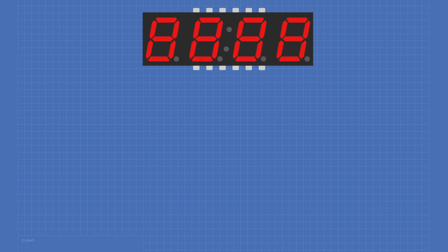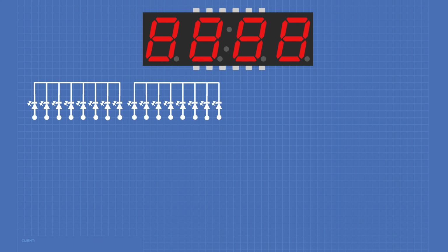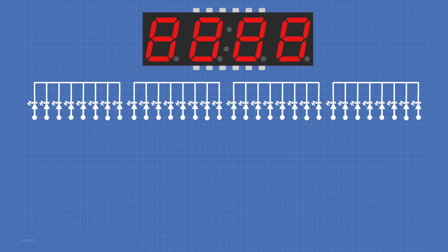In this experiment, we'll be using a 7-segment 4-element LED display, although the principles also apply to the 2- and 3-element displays as well. This display has 4 independent 7-segment LEDs. Now I'm illustrating common cathode devices, but common anode devices exist as well.